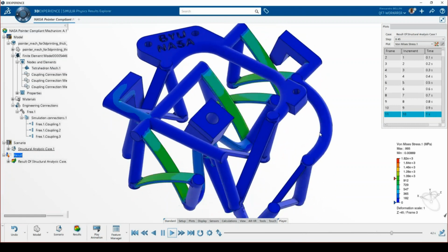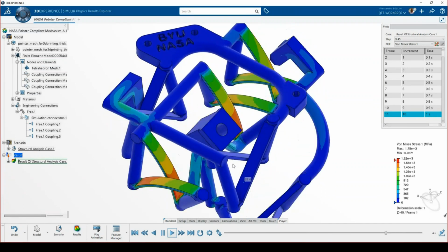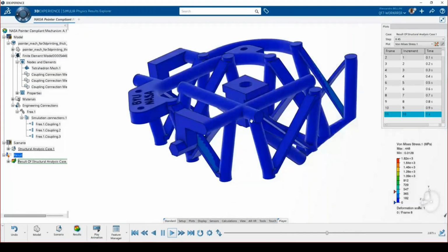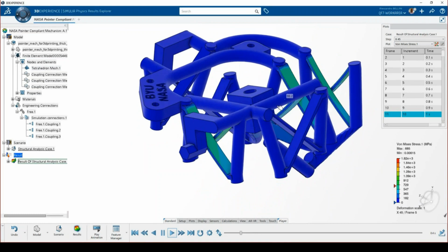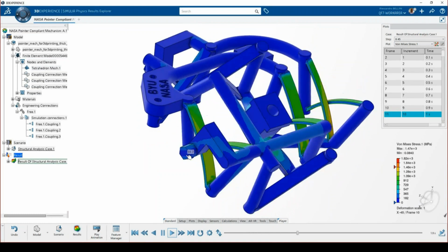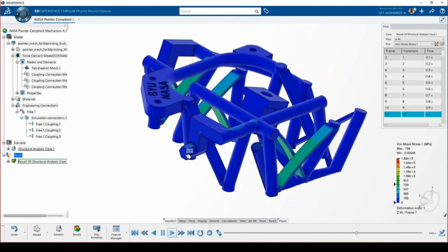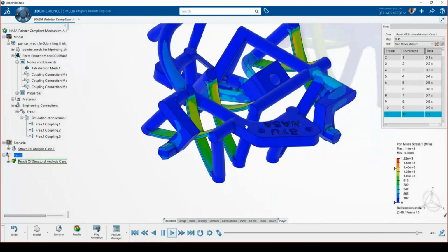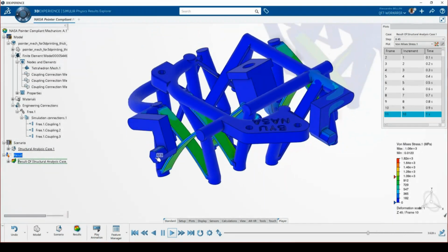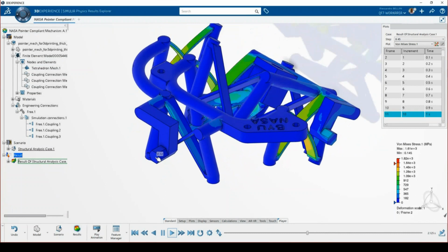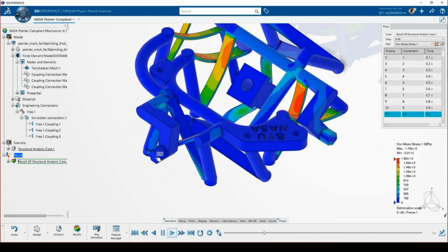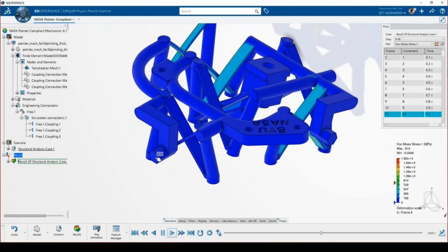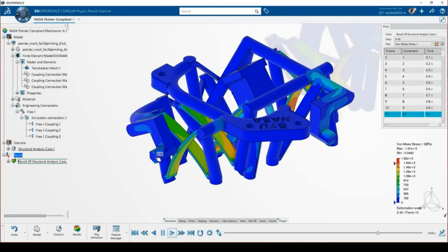And you can see all the steps in one analysis. So very easy to handle inside SSE and very interesting, very nice results. As you can see, I can also just probe the value on the mesh itself, for example, for the displacement. Here I just want to check the displacement when the other axis is rotating.